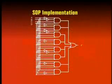The sum of product based implementation of the adjacent ones detector circuit is shown, implemented directly from the function table. The implementation uses the maximum number of gates. The total gate count is a single 8 input OR gate, 8 4 input AND gates, and 10 NOT gates. Altogether, 19 gates are required to complete the circuit. The increased number of gates increases the cost, the size of the circuit, the power requirement, and the propagation delay, which is of the order of 3 gates.